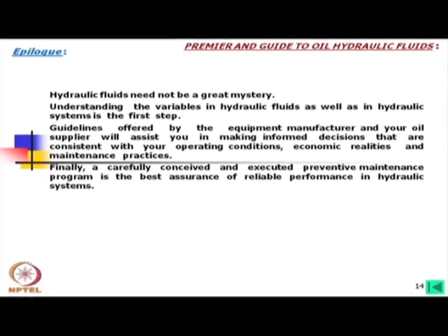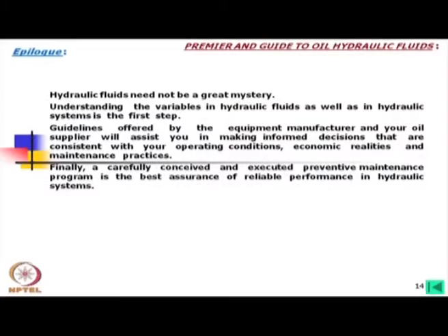This I would like to mention, that knowing the operations of a machine, the performance of a machine, efficiency of a machine, we can make a schedule for preventive maintenance, when we should inspect the oil, when we should change the oil.